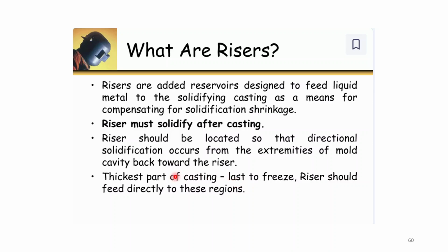So your riser should be above the thickest part, which is the last to freeze, so the riser should feed directly to these regions.